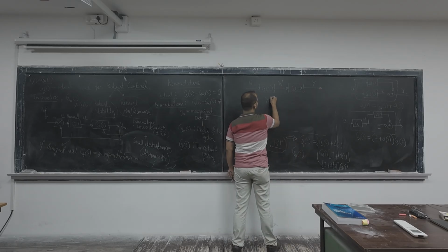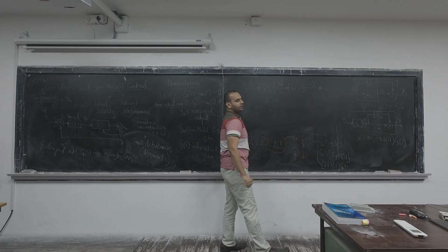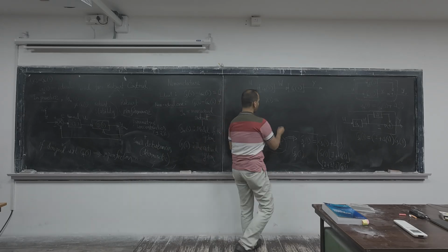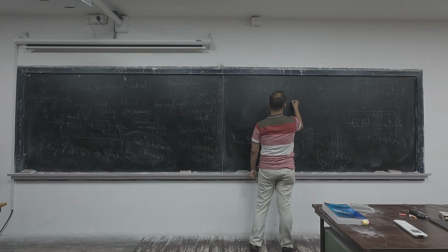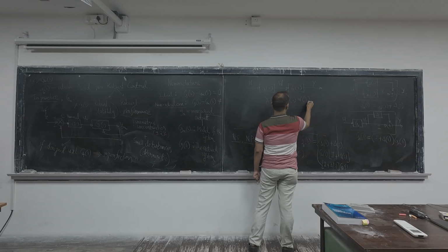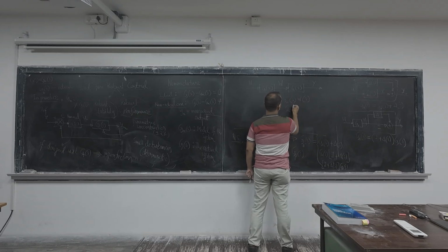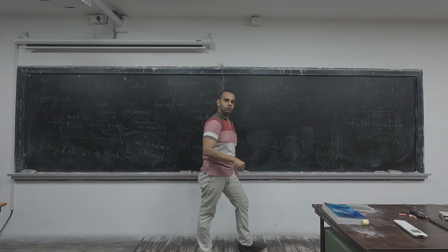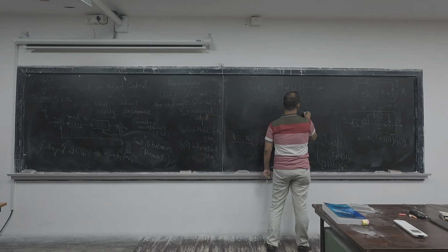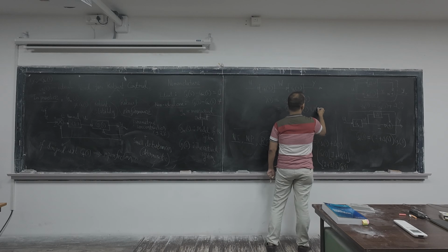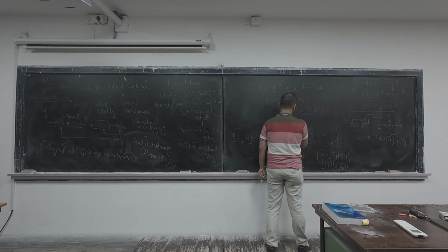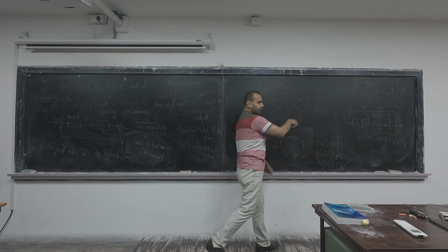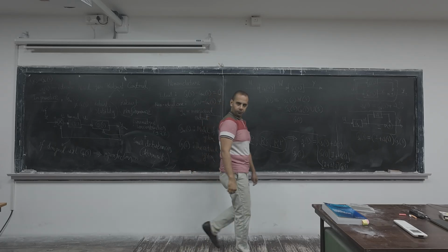Y of S, easily we can write G2 of S into W of S. The moment you do this, immediately it would be clear. Now W of S means G1 of S into U of S. Together we can call it G of S. Here also the same. Are you getting?